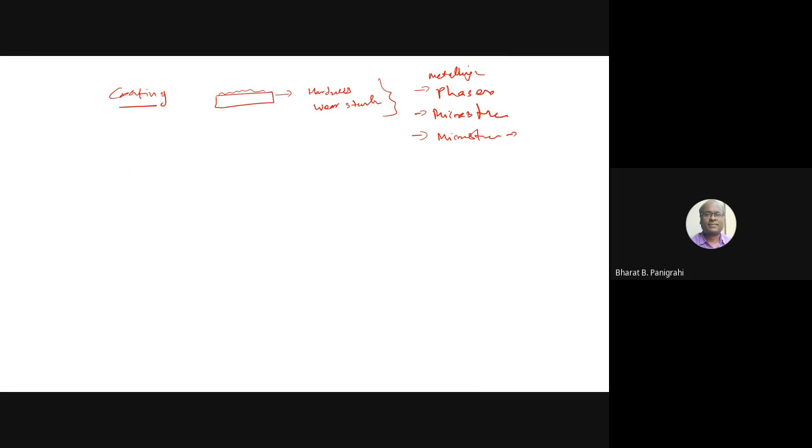Another side of work which we have initiated here is damage repair. You can think of a component, and assume that this component is damaged. What you do is electrospark deposition to restore the surface, and polish it, so that after polishing you have a smooth flat sample. This flat sample is then tested for a tensile test, compressive test or bend test, and you compare with base material of similar strength.